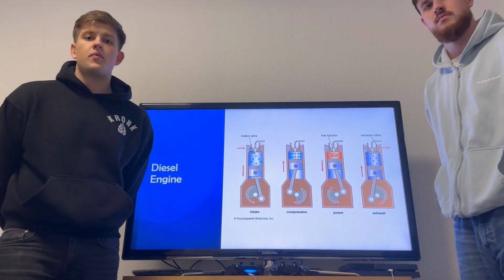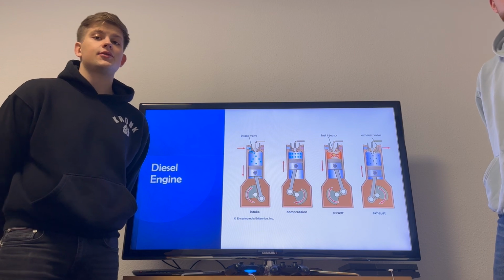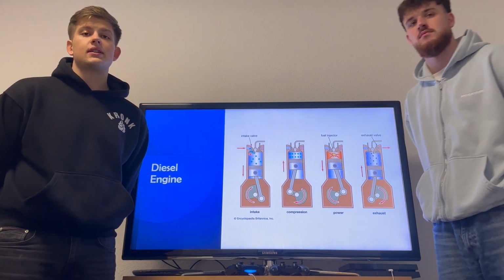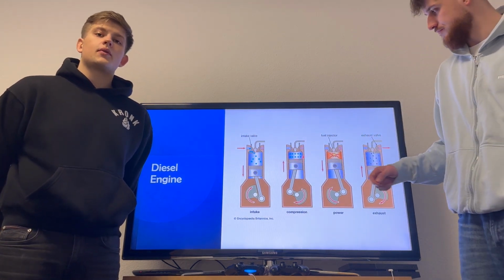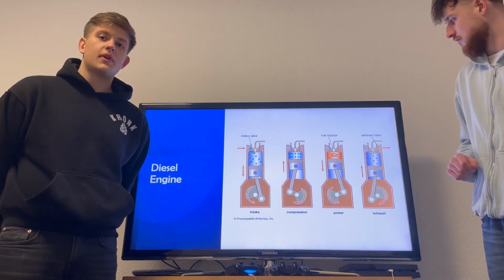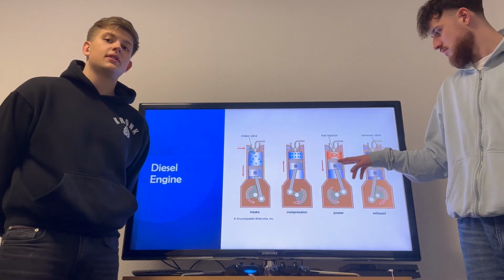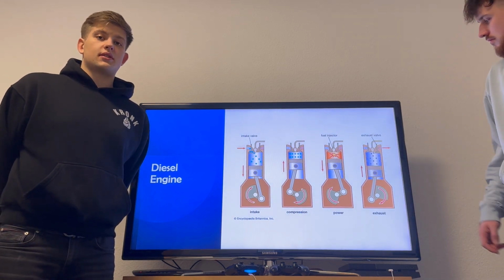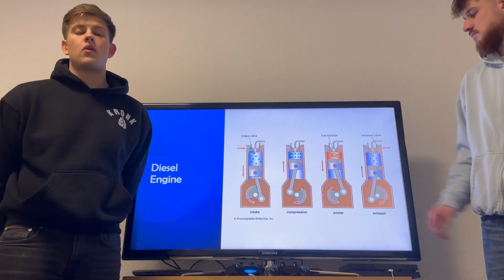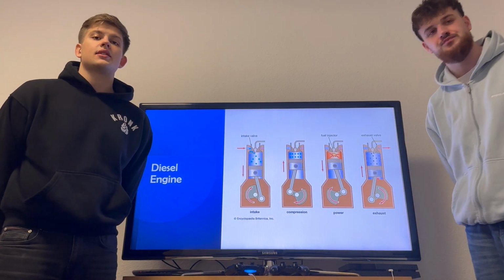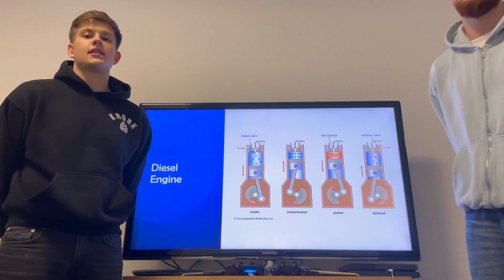The diesel engine operates on the diesel principle, involving the following steps. Initially, air is drawn through an air filter and compressed in the cylinder. Compression occurs solely through the piston without prior fuel mixture. Fuel is injected, and due to the high temperature and self-ignition of the diesel fuel, the self-ignition occurs in the cylinder, which drives the piston downward, creating power by expansion and generating mechanical energy. Finally, the burnt gases are expelled through the exhaust.